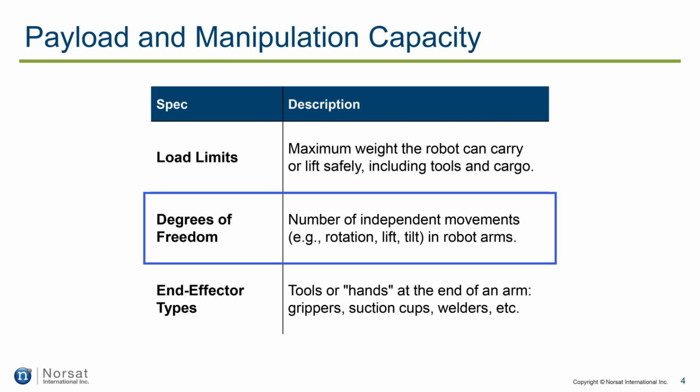For mobile robots, a differential drive moves forward/backward and turns, about 2 to 3 DOF, but can't move sideways. Mecanum-wheeled robots add DOF, enabling movement in any direction, including sideways and diagonal. More DOF means greater flexibility and accuracy for tasks like sorting, inspection, or assembly.